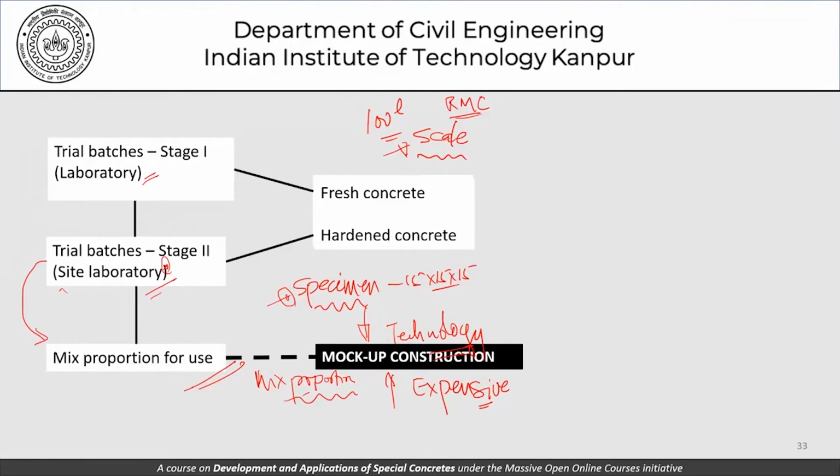In the curing discussion which we had, we said that in certain cases the water needs to be heated or cooled, or not only the water, but there was talk of some aggregates being heated or cooled. Now, if this is to be done, carrying out the proportioning in the lab is quite different from trying to do it at an RMC plant and then ensuring the temperature of fresh concrete.